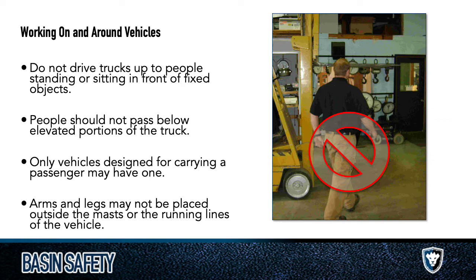Well, that can be deadly if you're behind an area where things are being loaded or offloaded, if you're not paying attention around a corner and there's a forklift being operated. Yes, the equipment operator, it's his responsibility to know where everyone is. I will agree with that, but I'll also say that if you're around a forklift and not operating it, give it some berth, pay attention, give a shout if you're coming around a corner and you know that the guy operating the forklift's on the other side, etc. A few other tips and tricks here.